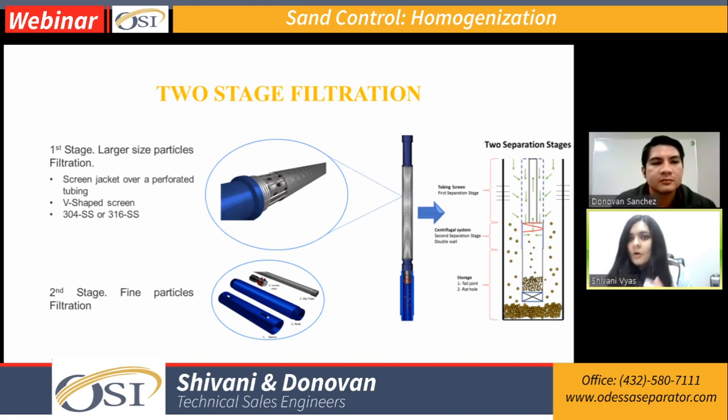have all those factors come into place, like Donovan mentioned: the velocity of the fluid, the pressure drops, and then below it, you have mainly three things that come into consideration. Your helix creates your centrifugal force. Your sleeve, just in case we're producing so much sand that whenever we have a cutting of the body, there is still an external protection so you do not lose the integrity of the tool, and now you do not have a fishing job.